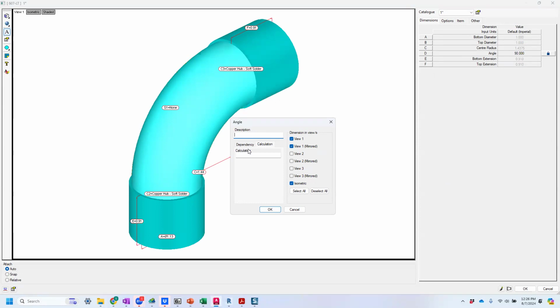So Ryan, right off the bat, is it possible to create a combination of a clevis hanger and an insulation saddle using 2 separate ITMs, or does this need to be done in one single ITM? Great question. If we were back in the old ITM in CAD MEP days, you could use subassemblies to do something like that. Unfortunately, with Revit, you're not going to be able to do that. You could theoretically use Revit groups. That could be an interesting way to do it, using 2 different ITMs.